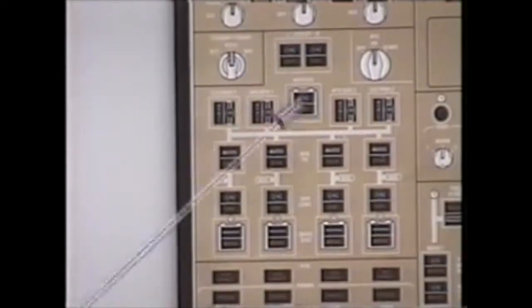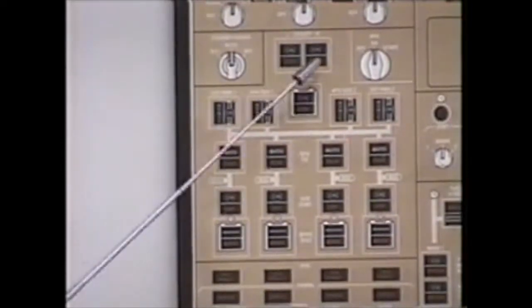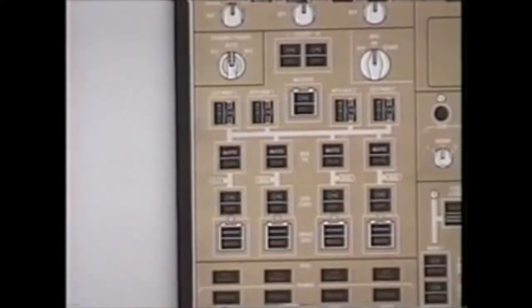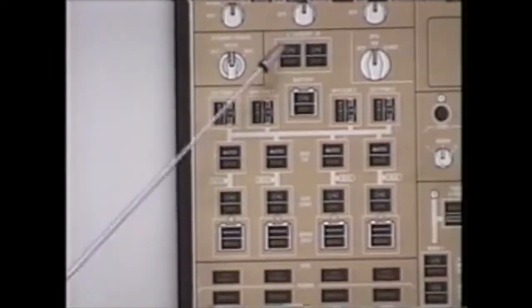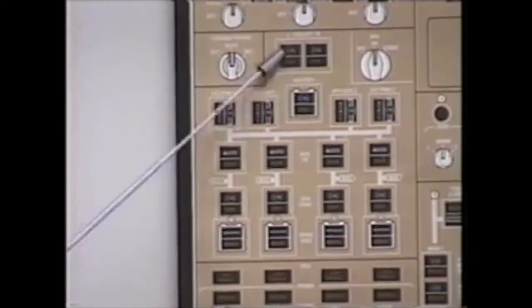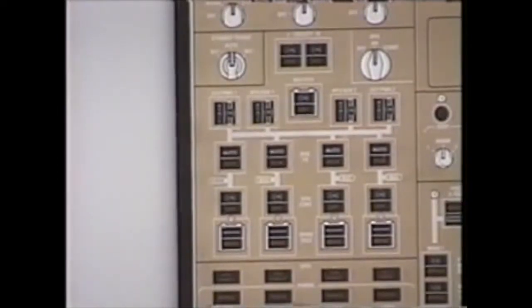If a load shed occurs, the off lights will not illuminate in the respective switch. Turning a utility switch left or right off will kill both galleys and both utilities on the respective side. It will not kill the respective AC bus. Below the utility switches is your battery switch. The battery switch controls both the main and APU batteries, which are guaranteed to last 30 minutes.